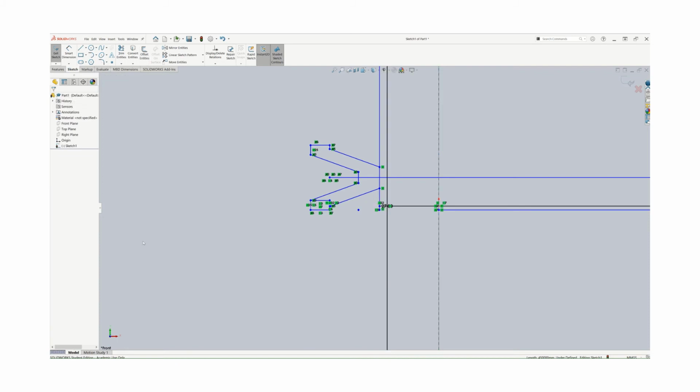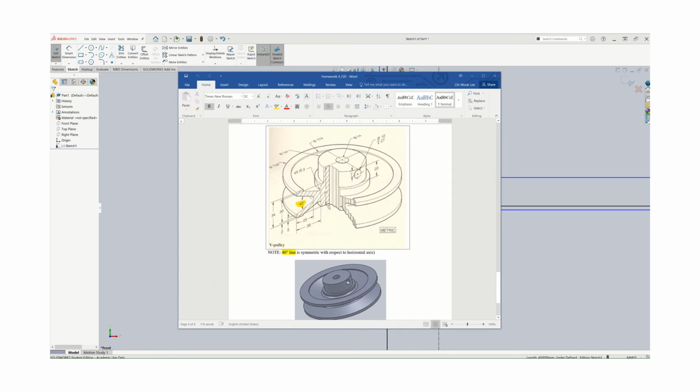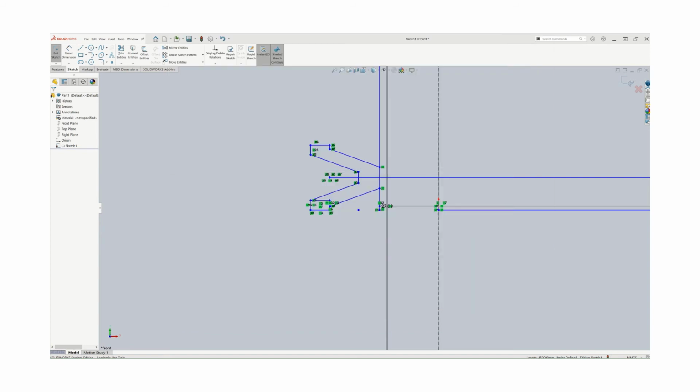And also if you look at this, the horizontal line has to be offset by a certain amount, and that's 50 millimeters up, so that our offset one is going through this line. So offset this line by 50, and it's going to be in the reverse direction. So basically I could have some of the elements that I trim again. Then I need to have that, oh, I think I did 50, but it's not showing.